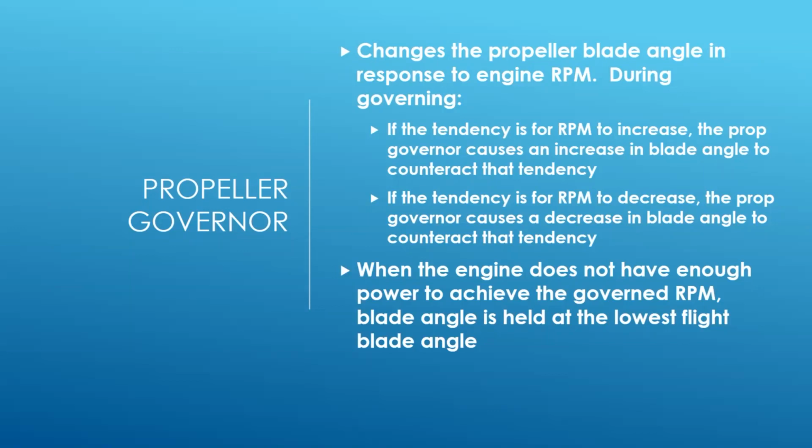We're in the ungoverned range, and it acts like what type of a propeller then at that point? It basically becomes a fixed pitch propeller. So if you're below the governed range, if you're below the range where there's enough power to be able to increase, the blade angle's now locked at its minimum pitch. You add power, the propeller is going to speed up. You reduce engine power, throttle, it's going to slow down until you get to that governed range. And then if you increase or decrease power in the governed range, then the prop governor is going to try to maintain a set RPM. Okay?